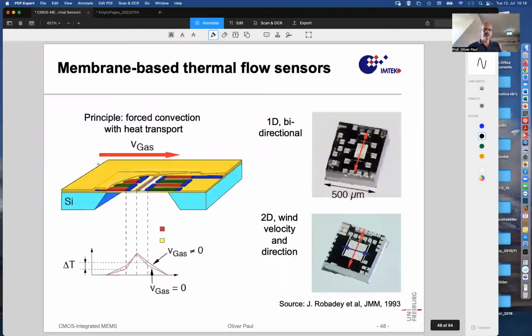And so this is basically the situation when Felix Meyer started designing sensors. Actually, I designed some of his sensors at the beginning of his thesis, so that he could have a steep start, and the outcome after his thesis looked like essentially membrane-based sensors with a central heating resistor, and then thermopiles on the left and right.